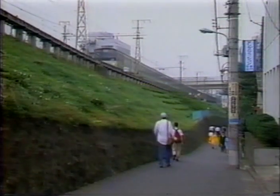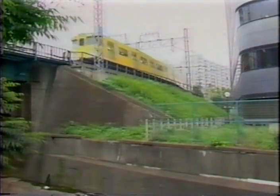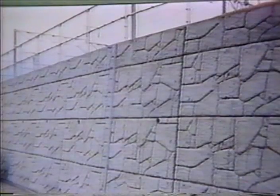In crowded Japanese cities, to save space, railroads are frequently built on embankments of geosynthetic reinforced soil. Here we see gabions of bagged gravel wrapped in layers of geogrid, backfilled with local soil. These flexible walls are often faced with concrete panels.